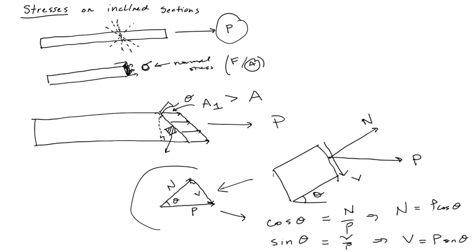Okay, now this is valuable because now if I give you this load P and some angle theta for the cut, I can now tell you what the components of force are normal to the cut and tangential to the cut. Okay, and so now we're just one step away from some more insight into what stress is.